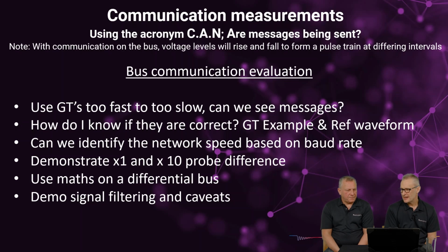again, you stopped me dead in my tracks. How do I know it's not PWM? How do I know what wire I'm on? Use the guided tests. The guided tests have a default setting, so they'll get you a measurement on screen using the right probe, with also an example waveform. So how do I know if what I'm connected to is the right wire and the right bus? We have example waveforms in our guided tests, so you'll be able to keep the example on screen using the reference waveform feature.